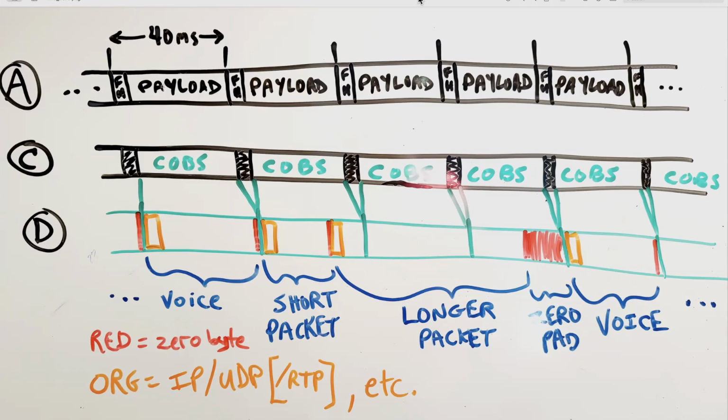You could just use the TCP capabilities that are in your host computer's existing network stack, which already has guaranteed delivery and reorders data that comes out of order and stuff like that. And it's bulletproof after decades of being used on the internet. We've made a preliminary decision to just ignore the whole problem of data loss and data getting out of order for now and implement with the assumption that everything's just going to come when you need it, and you put it together in order and all you have to do is do the COBS decoding.